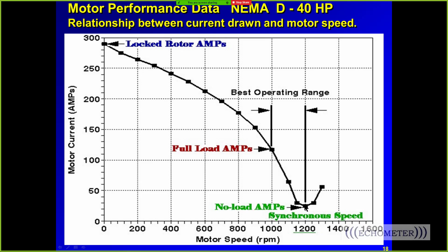Low load is a minimum current, and then the current increases to lift the rods, and the motor slows down. And look, the amps that you're using go above the rated amps for burning the motor up. So during the peak use of amps to lift the rods, often the amp draw is above the motor rating.